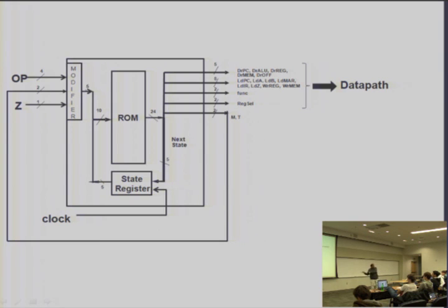All these kinds of things go out from the ROM, and the additional things that go back into the control unit are the M and T bits, which are the modifier bits. The modifier circuitry takes these 2 bits along with the opcode, 4 bits, and the Z bit register, and then decides whether it wants to modify the top 5 bits of the address or not. If it is not required, then it doesn't modify it. If it is required, it is going to modify it. Is that idea clear?